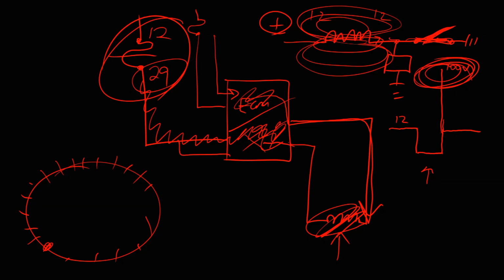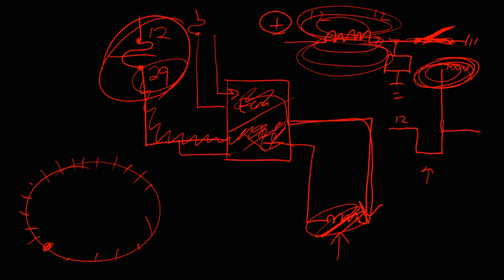Couldn't communicate. No communication, no start, no spark, no injection pulse, no fuel pump operation. Start doing my power and ground checks, and that's when I saw 29 volts on 2 of the power feeds, because this was split. I went around in circles trying to find out where that 29 volts was coming from before we found it. Because I might have had a student check the fuse and it was lit on both sides and maybe didn't pay attention. I don't remember exactly the whole process, but really, really cool case study.